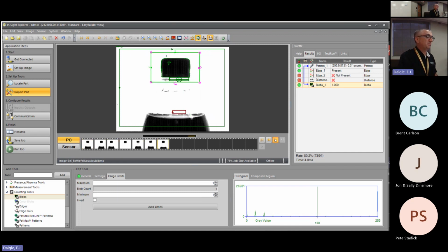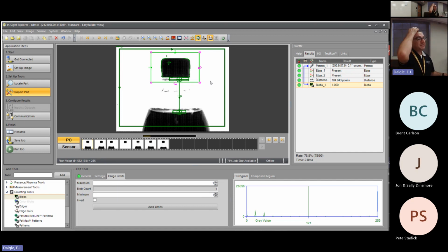What we just did, mind you, there are people that literally make a living setting up inspections like this, going out to the site, lighting it up, communicating. The next thing I would do, and why Cognex is such a powerful utility for what we do, is when you work in the world of PLC, if you're working with a Rockwell or Allen Bradley controller, Cognex has add-on profiles that directly embed themselves into your Studio 5000 or RS 5000 code. What that means is when I add the add-on profile for whatever camera I'm using, the PLC actually thinks it's a module within the rack. So all the I/O is communicated right across between the PLC and the camera.